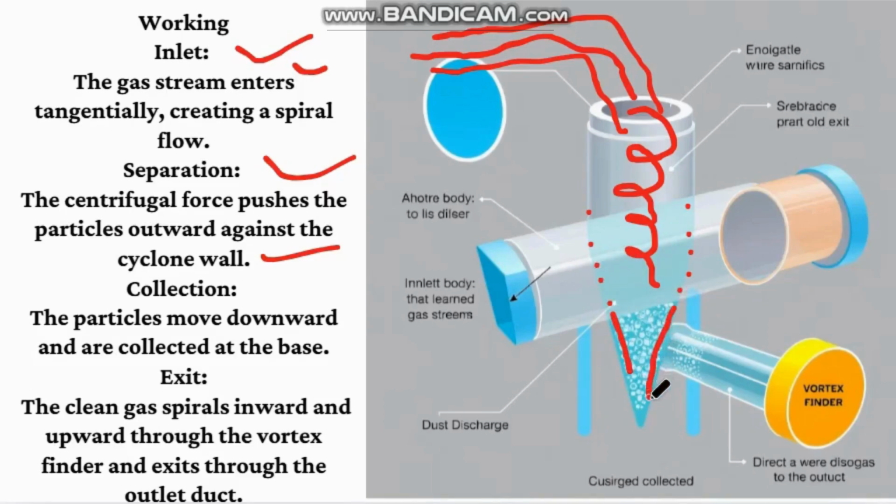and the larger particles are collected in the collector bin, and the finer particles which are suspended in the stream of air are removed through the outlet. In this way, the larger or solid particles are separated from the stream of air by using the cyclone separator.